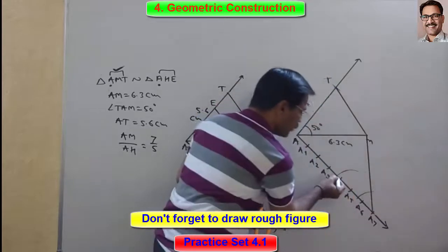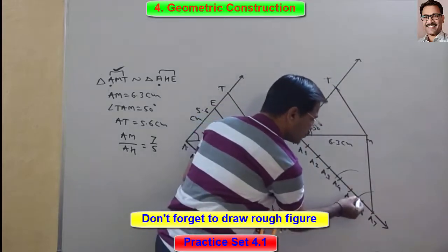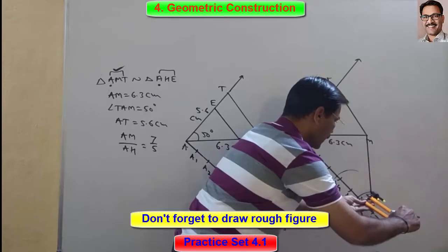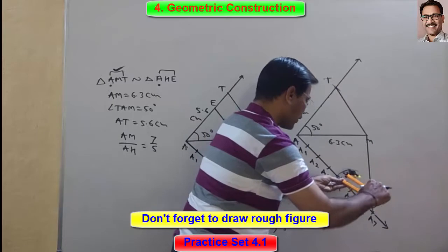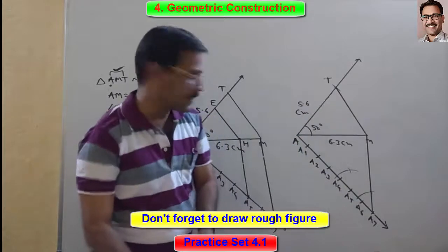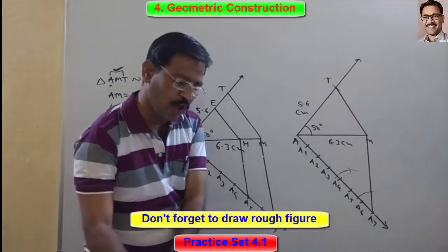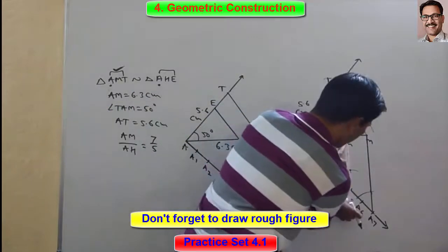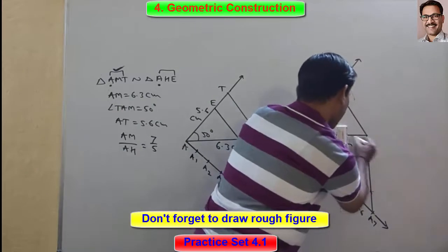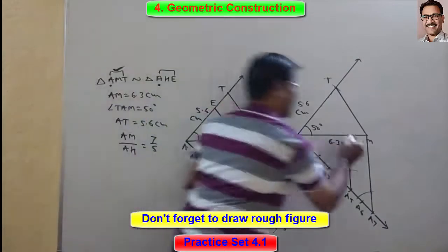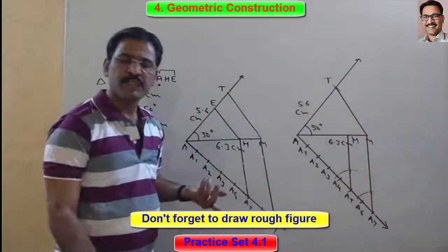Okay, here these are the three new points which we can get. 1, 2, and here this one is 3. So now in the compass I'll take this one. Now just adjust here whether it is the same or not. Now from this point draw one arc here. After getting this point, we have to draw from A5 through this new point the parallel line. Second, understand? See here. So which point is that? H is there.